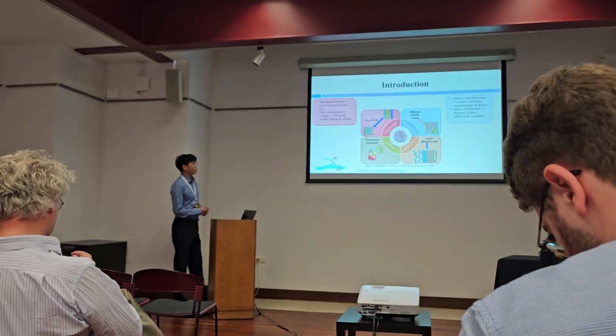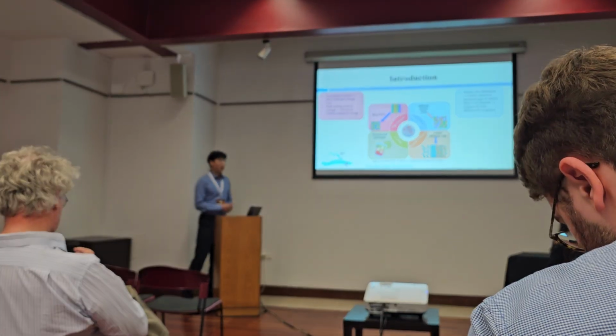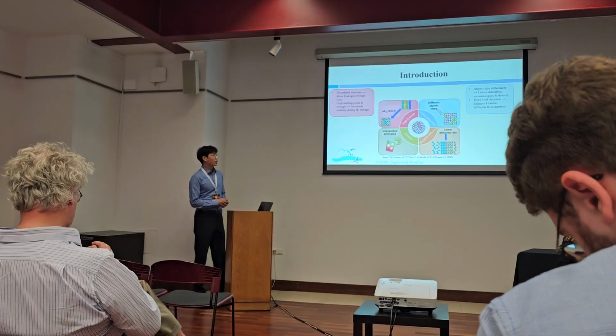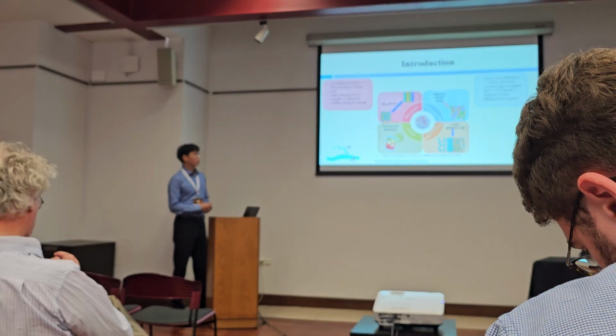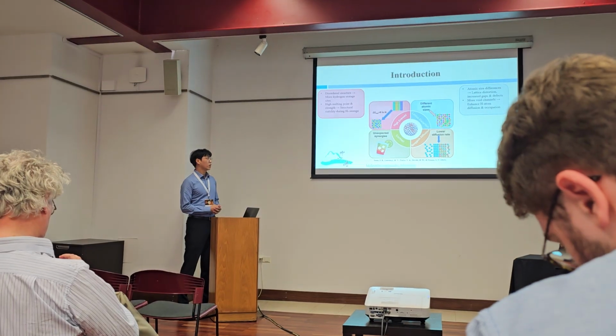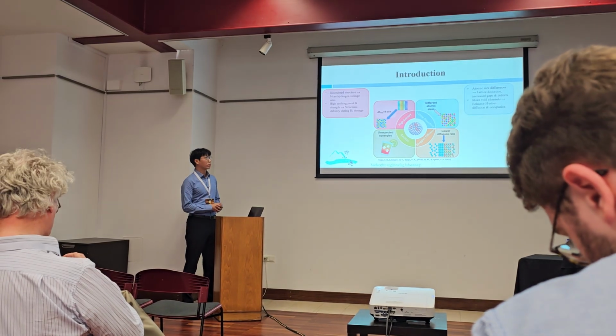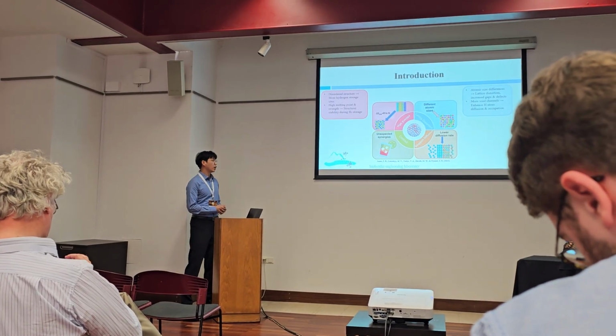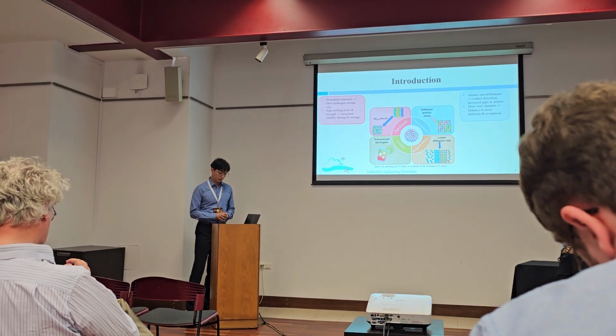Second is the lattice distortion effect. Atomic size difference makes lattice distortion, increasing gaps and defects. It makes more voids, which enhance hydrogen atom diffusion and aggregation.